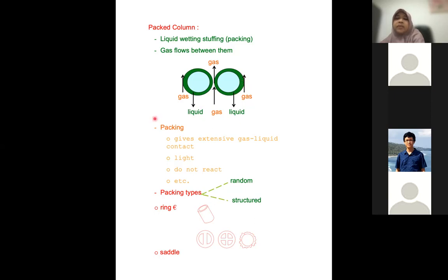So a good packing is one that gives extensive gas-liquid contact. It should be light as well, not too heavy, and should not react with the solute.